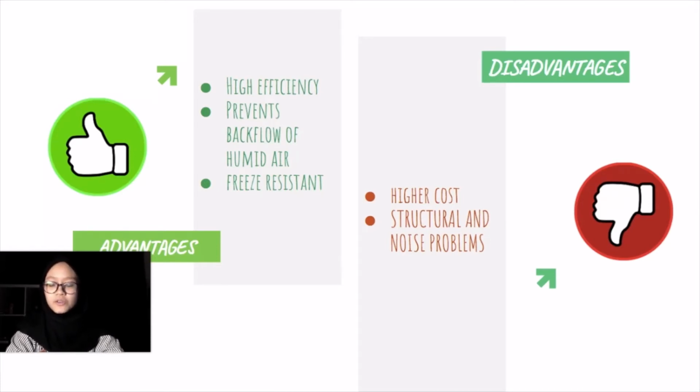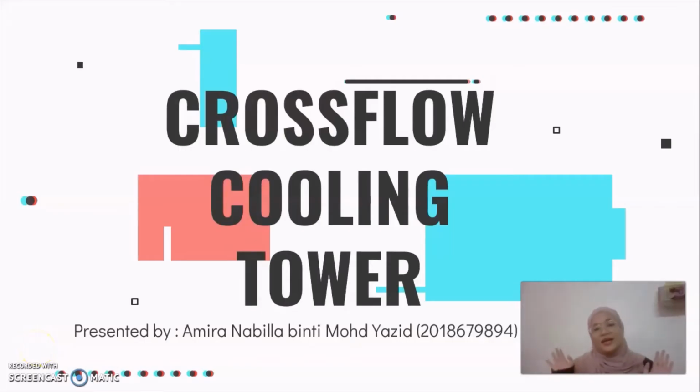The disadvantages of counterflow cooling towers is that they have higher initial and long-term costs due to the pump requirements, and structural and noise problems may be present due to the design having a fan at the top of the tower.